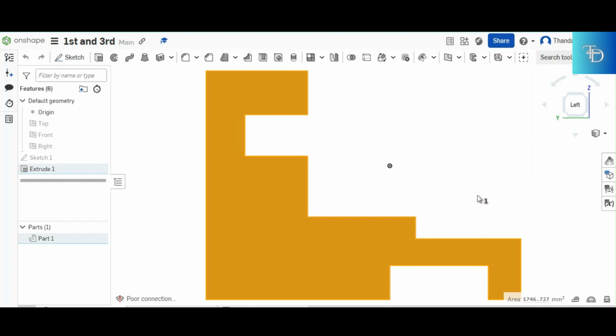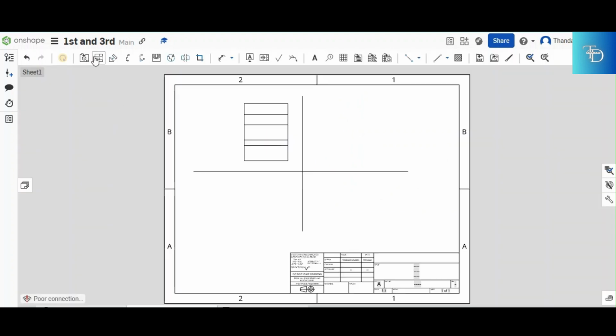So you take this shape as it is, you go and put it where? On the second quadrant where you are supposed to place your left view. All right, then here we are. We have the second quadrant empty and ready for the left view, and then you project the left view from the front view, which is something exactly like that right there. This is how you come up with the left view. You put it right there. Don't worry about how to draw it right now. We're gonna get to that after I'm done with the explanation.